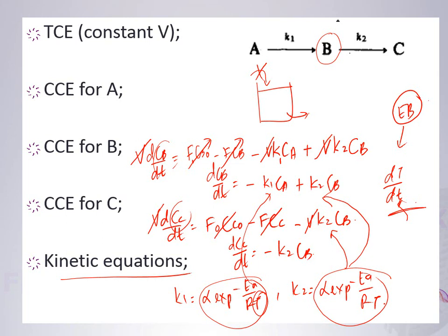Okay, it will take time for the temperature to come down. You imagine, it's not a small glass we're talking about in the house. We are talking probably about a 60 ton volume of reactor, or 20 ton volume if it's a small reactor. So it will still take time for the temperature to go down. Remember, you have a stirrer. The stirrer will make sure that the temperature is evenly distributed throughout the whole system.